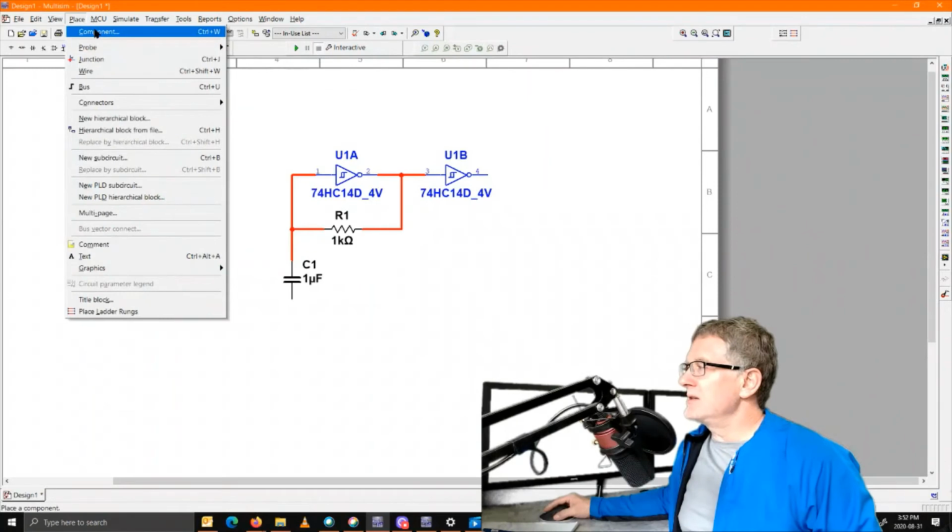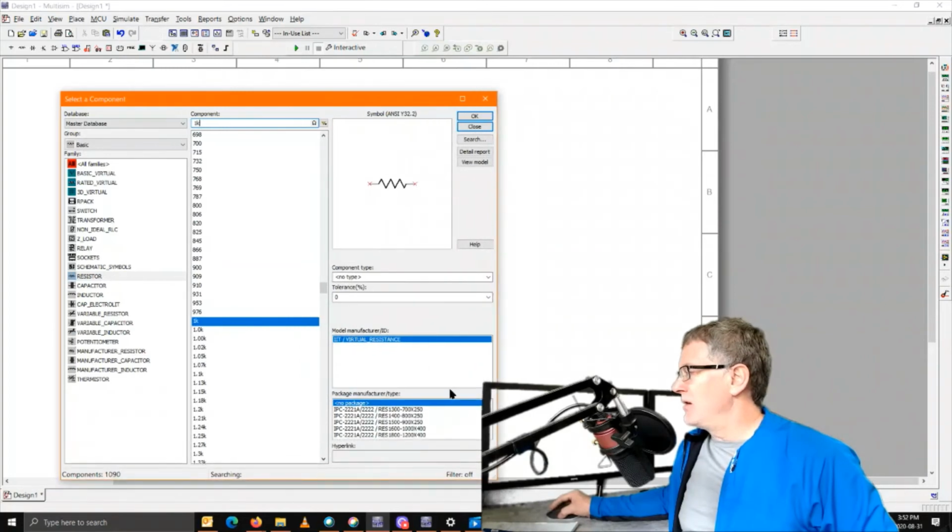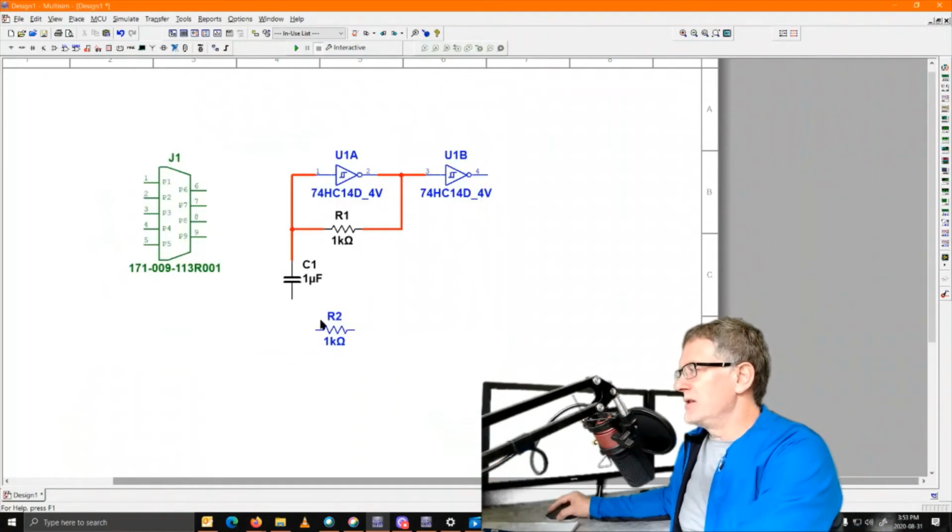So when you go in to place a component, such as a 1K ohm resistor, so here's resistor 1K, what it does is over here, it gives you the option of picking a footprint for that part. So the default is no package, and then there is all kinds of different packages that you can pick. So if I pick, here's one here, 1600 by 900, that's probably like 1.6 inches by 0.5 inches. Sorry, that's not a 900. So I can pick that. Okay. And then it puts it down. You can see as soon as it puts it down, it's blue, while before it was black. So a black component does not have a footprint associated with it, and a blue one does. This is if you've got the default color scheme.